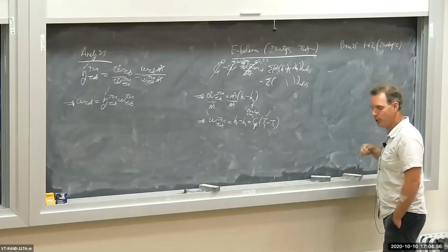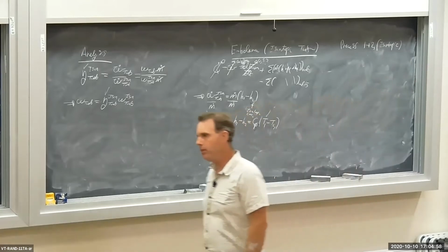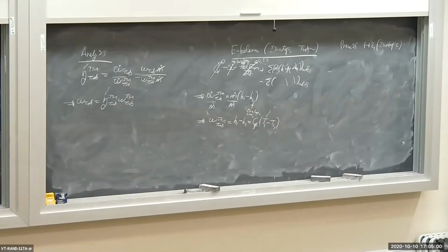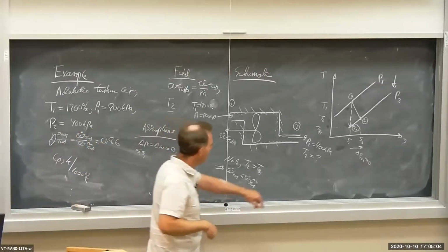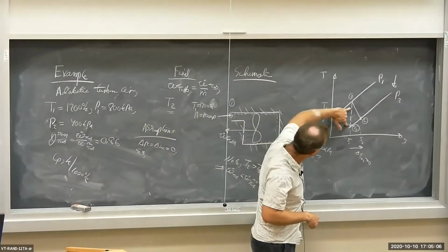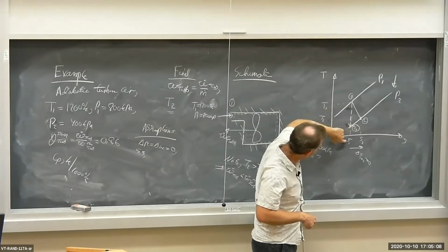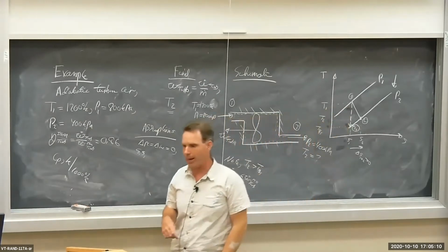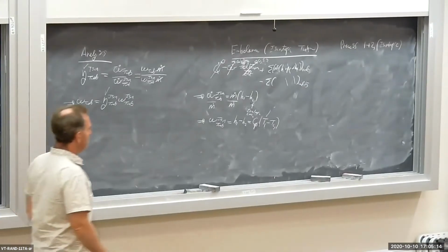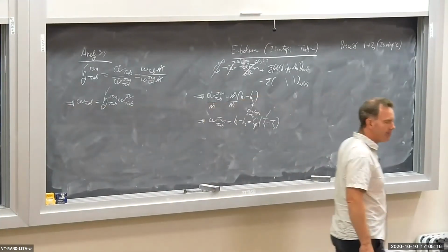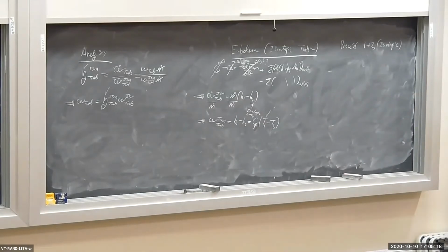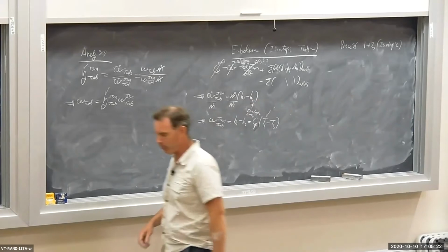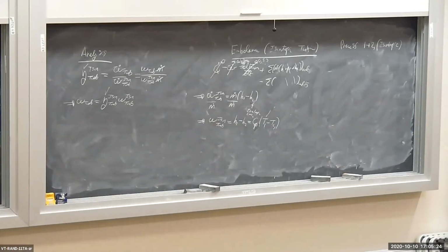So that's isentropic expansion in the turbine, the reversible isentropic adiabatic turbine. 1 to 2 sub s is vertically down, so s1 is equal to s2 sub s. So for constant specific heats, I can go to a property relationship. Let's have a look. Let's see if I can pull out a property relationship for constant specific heats.